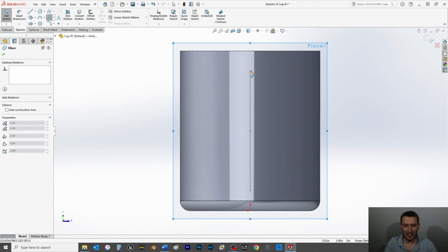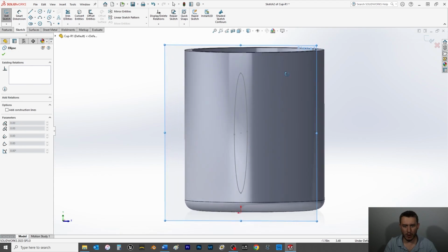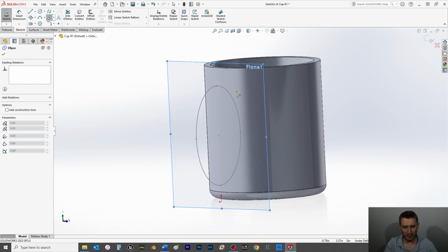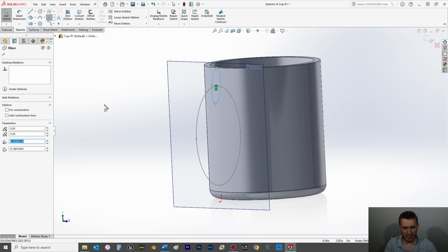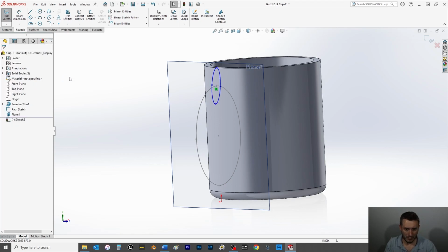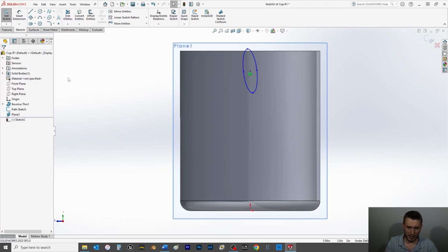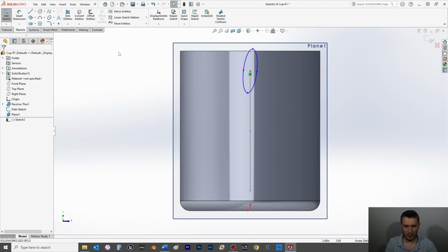So with that, I'm going to rotate it back to more of an isometric type view, and I want to make sure that I select this top point of our previous ellipse sketch, click and drag out, and we'll do something like this. Now from here, I'm going to go Control 8 to bring it normal to, again on the back.